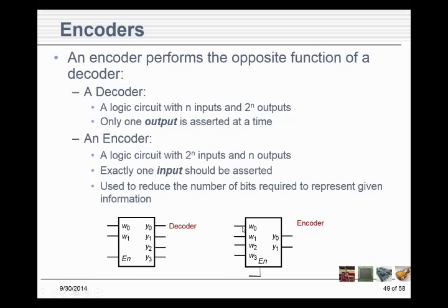And then if this is asserted and this is enabled, that's saying that only this one goes high. When I've got 0 here, these are 0. When this one's asserted, I have a 0, 1 here. When I have this 2 asserted, this is 1, 0, or 2. And when I have a 3 asserted here, then this becomes 1, 1, or a 3.